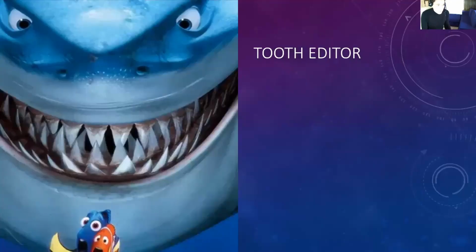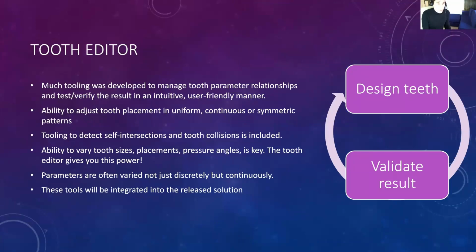That leads us right into the tooth editor. Now, after all this study I performed, much tooling was developed to manage all these relationships and give you the ability to adjust your teeth placement and sizing and pressure angle variation, all that stuff, appropriately so that all the constraints are observed.